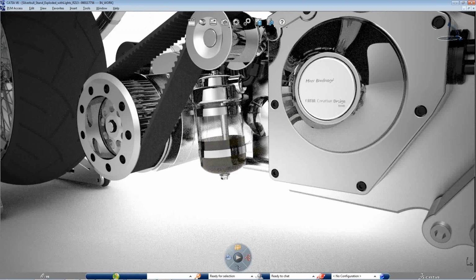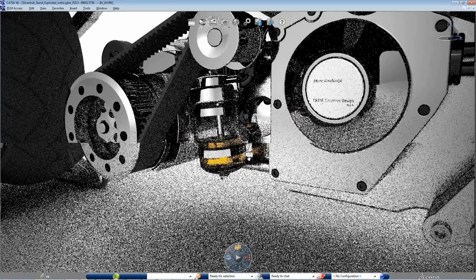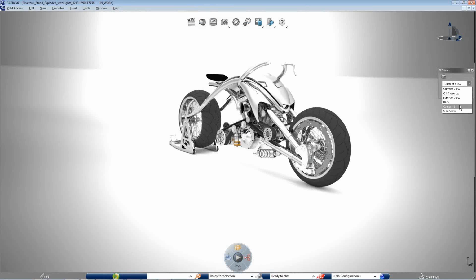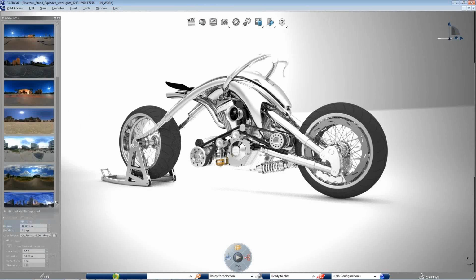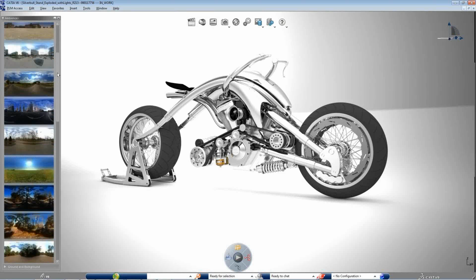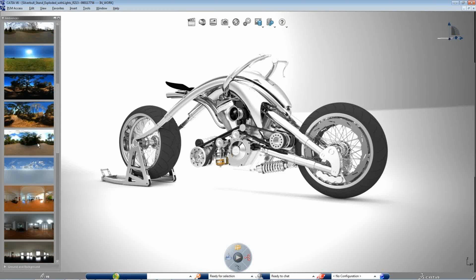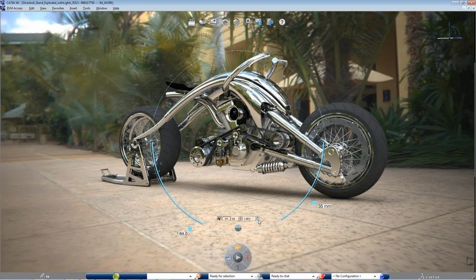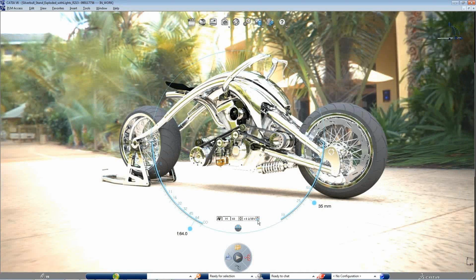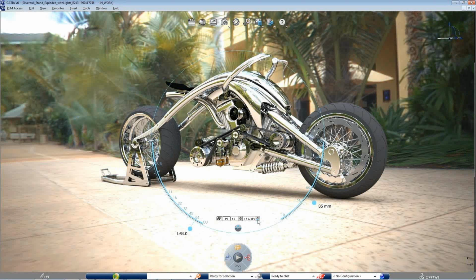And then if you need more precise and more accurate visualization, then you can just activate the interactive rendering mode, which means that now you have all the ray tracing in terms of reflections, shadows, diffractions on the glass, but also the global illumination in terms of lighting and shadows. So for example here, we want to see now in ray tracing and global illumination how the design is perceived in different environments. So again, just by selecting the HDRI environment, you can bring back the lighting source, but also all the reflections of the environments and the reflection of object to object. And with the live rendering,